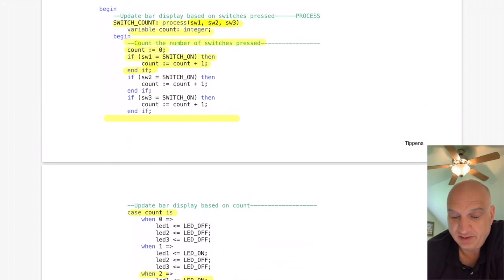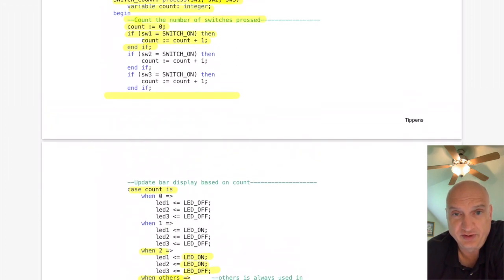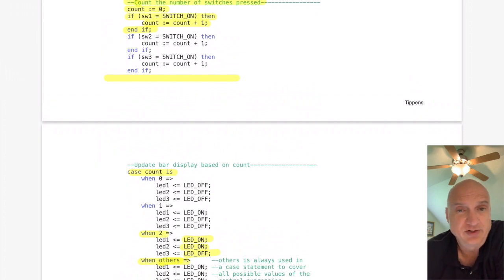But when we write this behavioral description the way we've done it here, it could potentially go through an optimization process and find the best set of logic to generate the circuit, if you haven't done a very careful job of doing your Boolean equations, really. It's up to human error at that point. The big takeaway is, no, it's not less efficient to do it this way. It doesn't really matter how many lines of code you have, unlike in a programming environment with C and such, where it does matter how many lines of code you actually have.